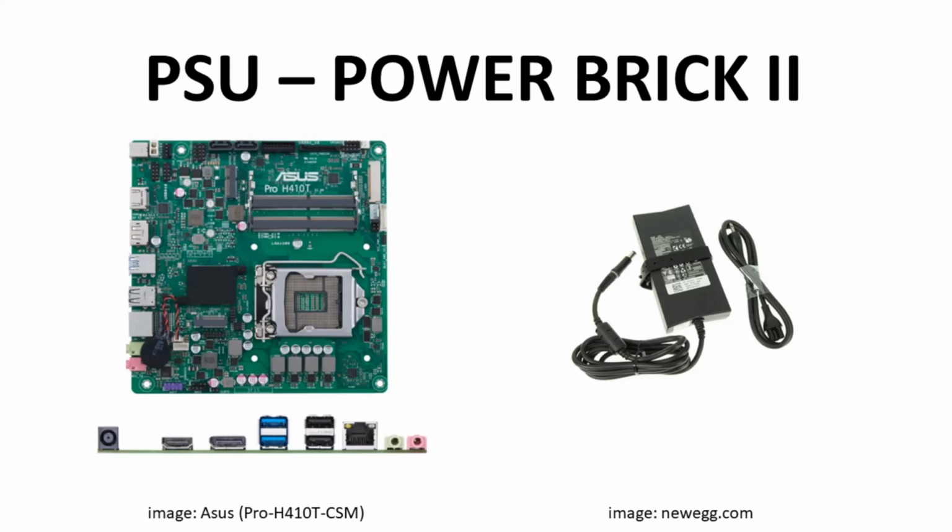The motherboard does the rest of the work in stepping down the higher voltage to feed whatever voltages the components need. The second option involves a little 12 volt connector, which is typically right behind the barrel jack connector. This is either a 2-pin, as shown on this board, or a 4-pin connector. You could power this board from a Pico power supply. You could run a 12 volt line to this connector and power the entire motherboard. Of course, you would need to run a separate line from the Pico PSU to a jack on the back of the case to access whatever power brick you have.